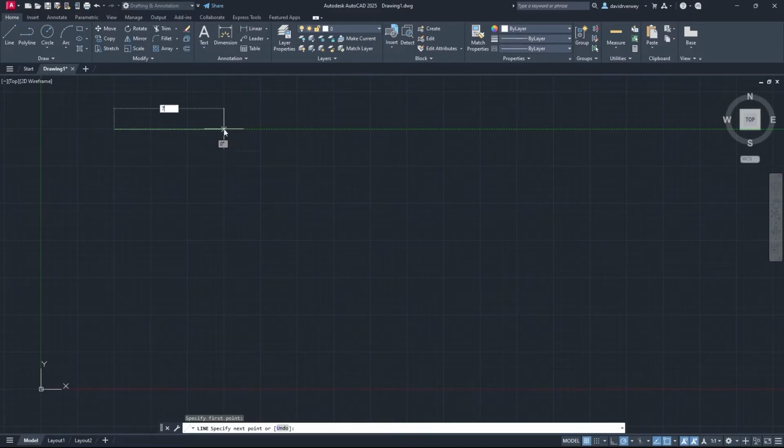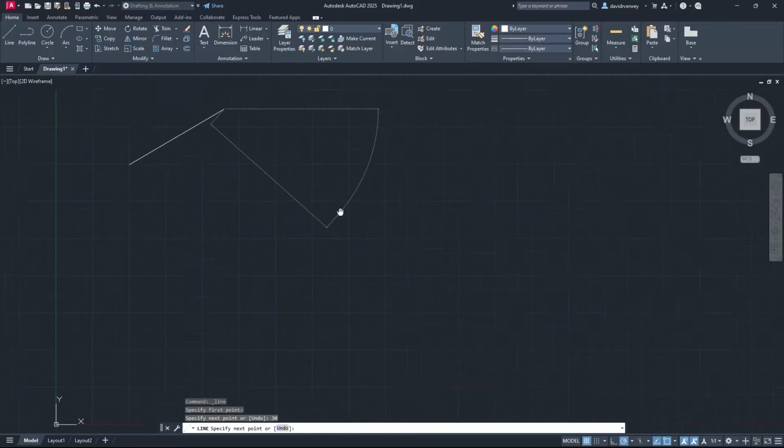So right now we're just going to type in 7.5 on our keyboards because it's automatically set, as you can see, to that distance that I have. You can also specify an angle if you press Tab, if you want it to be at, let's say, a 30-degree angle. Press Enter and it's now at a 30-degree angle.